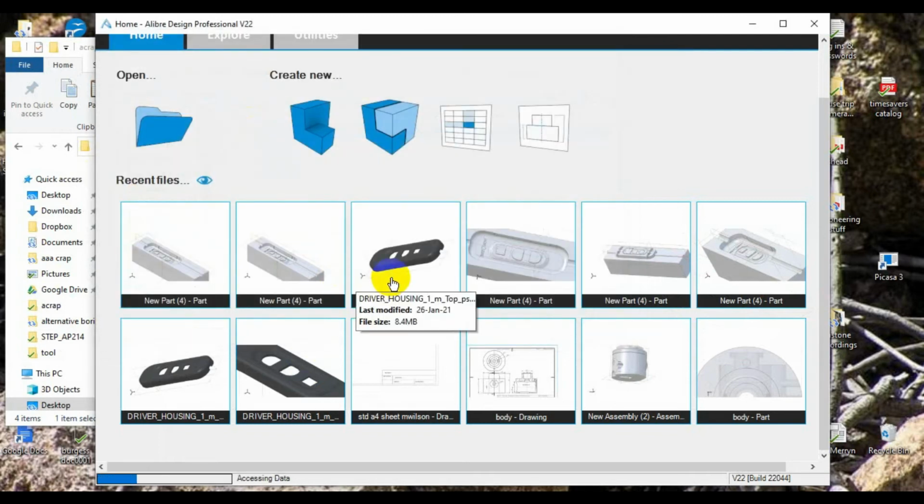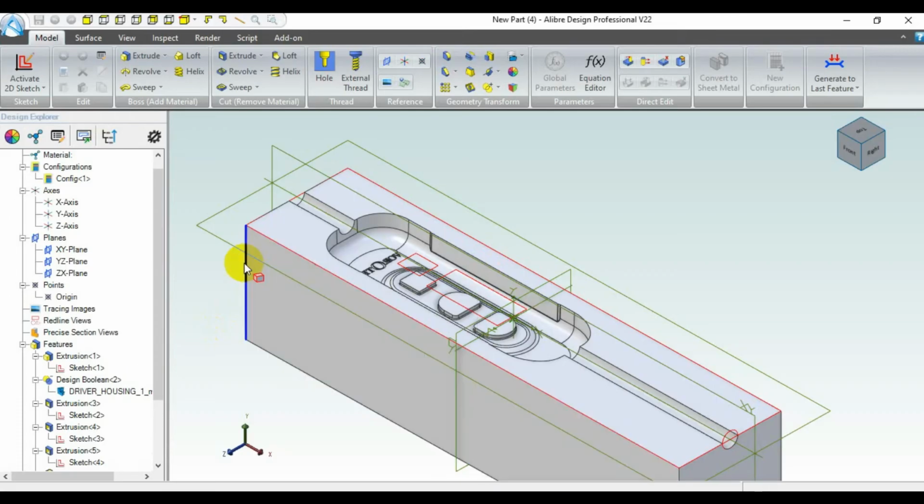So two copies of this cavity. Right. Now, theoretically speaking, if I import or boolean the existing molded part into this, and then create a core subtracting the molded part from this, it will create a core with the appropriate side of the tooling active.